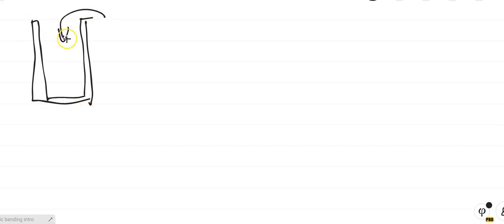And we just threw concrete in there, we just dumped it in there and left it to harden. Okay, and take the forms away. We'll have a rectangular concrete beam. But we just can't dump it in there, because we've got steel bars in there. We need to vibrate it.